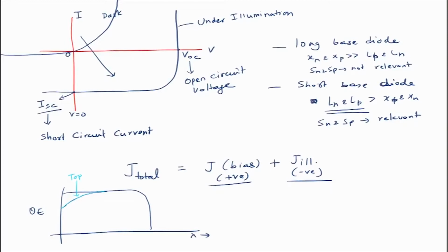and if your quantum efficiency is decreasing on the higher wavelength side, then you know that you have a decrease mainly from the bottom part of the solar cell. If you have a decrease in the middle, it comes from recombination taking place somewhere in the middle, or some other effects. This will be helpful for you to look at your data yourself if you work on solar cells, and analyze which of the layers may be playing an important role, especially in the context of bilayer junctions like PN junctions, wherever you have silicon kind of solar cells.